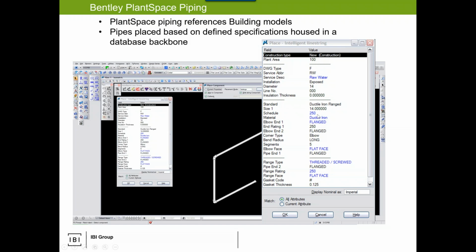And the other stuff it does ensure is it protects against the type of fittings. So this one here, it's what we have called a long elbow. That means it's not going to be an immediate 90 degrees. That means I need room to have the elbow. And if my pipe is super large in diameter, I need a lot of room to turn it. Therefore, as a designer, I might not want to turn it. But as a BIM coordinator, I want to make sure that if there's a limitation based on the spec, that the people have that at their disposal.